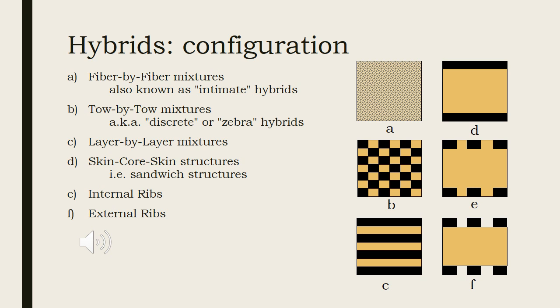Tow by tow hybrid composites are produced by combining fibers into fabric, either by weaving or by knitting. The vast majority of tows employed in woven, braided, or knitted reinforcements comprise low twist or untwisted continuous filament yarns. Three-dimensional technical textiles can be produced by weaving, knitting, and braiding.